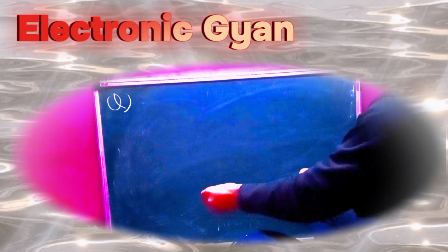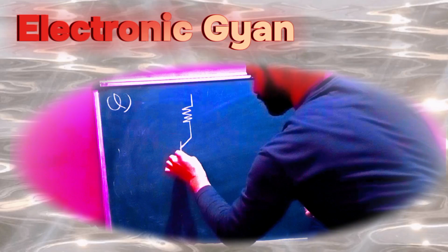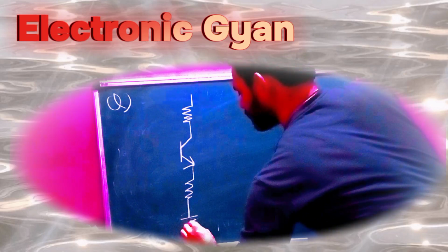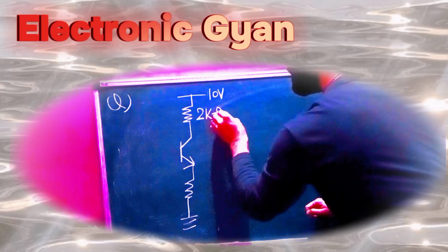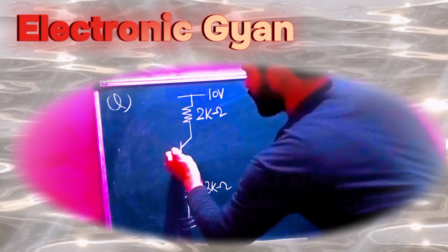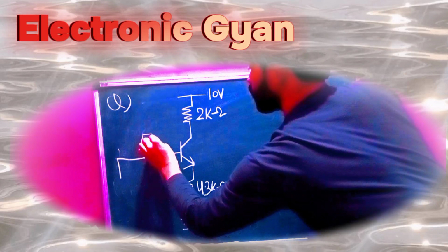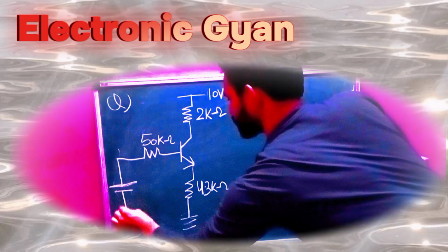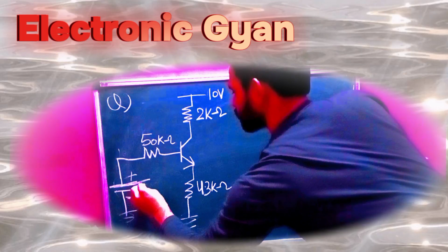The equivalent circuit for the common emitter amplifier is obtained as follows. This is my collector resistance, this is my NPN transistor, and this is my emitter resistance. This is my supply voltage of 10 volt, this is my 2 kilo ohm resistance, and this is my 4.3 kilo ohm emitter resistance. This is my base resistance of 50 kilo ohm, and this is the Thevenin voltage that we have obtained, positive and negative, 5 volt.